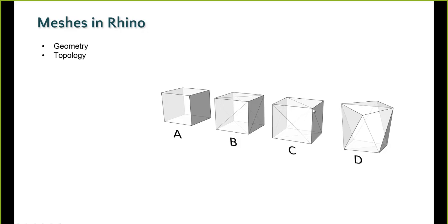The same with vertices. A vertex in the middle would have these four faces. It can have more or less than that. But if it's not completely surrounded by faces, then it's considered a naked vertex as well. And that can be useful in a lot of cases. And we'll see that, I think, on Wednesday when we're starting to look at physical simulation of stuff.